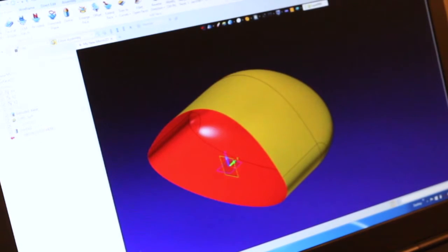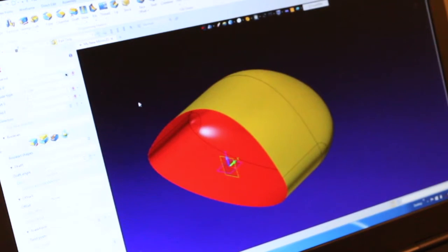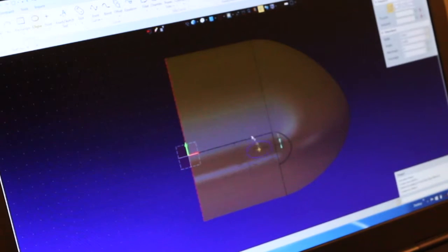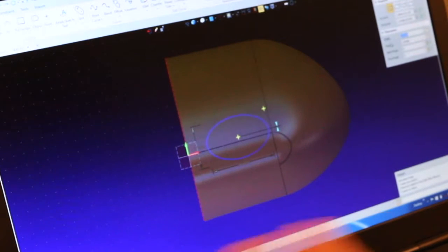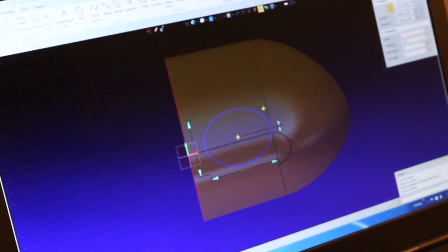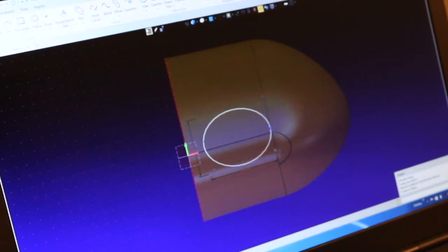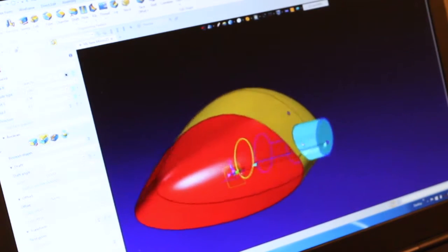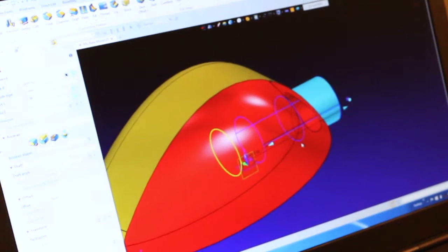We're going to need to mount this to the vehicle as well, so I'm going to use my solid shape tool. I'm going to extrude and I'm going to add. I'm going to put a sketch over here. And in this sketch, we're going to use a kind of an elliptical shape. Again, just kind of playing with some conceptual design. I choose OK. And this is the power of the hybrid modeler, being able to do solid and surface modeling with the same tool sets.